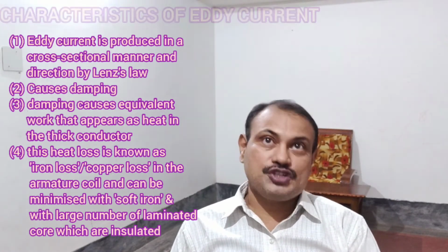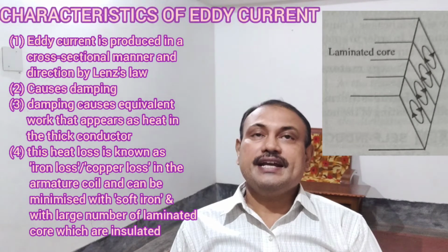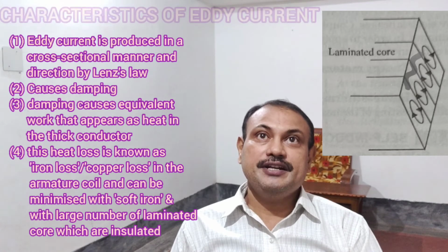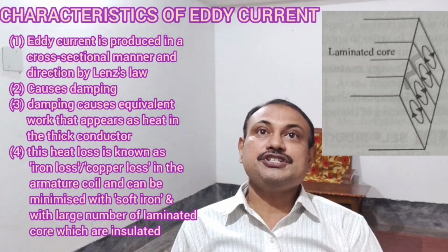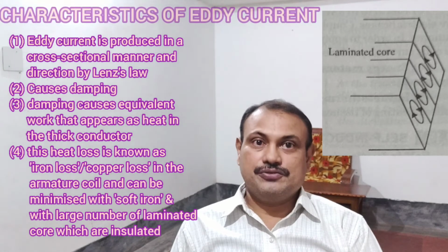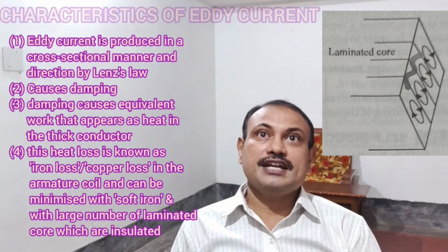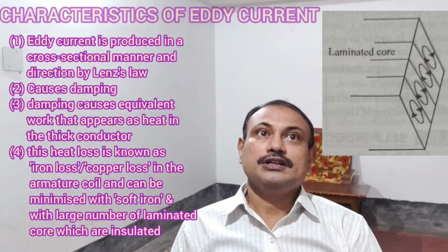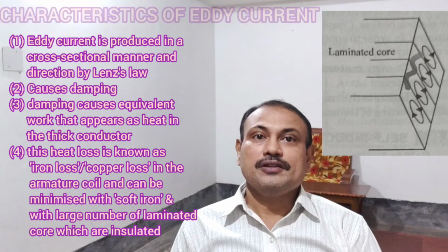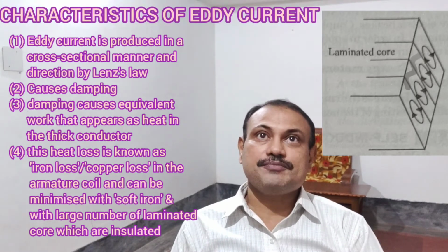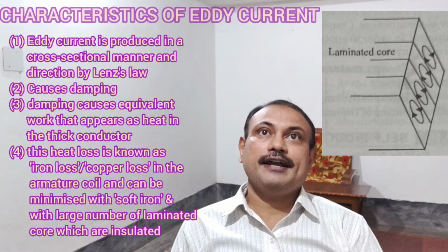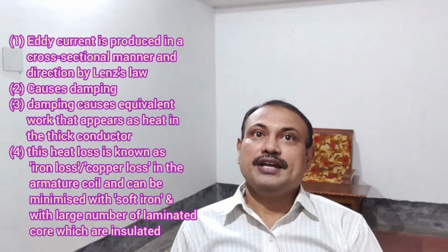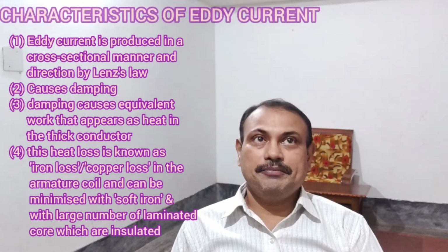And while laminated, if you see the picture, the interface regions of the laminated sheets will have opposite eddy currents induced. That induced eddy currents are opposite in direction. One is up and another is down, and therefore the effective losses will be minimized. They will cancel at each of the interfaces, and finally only the extreme components will be present. That is how the eddy current can be minimized by making it laminated.